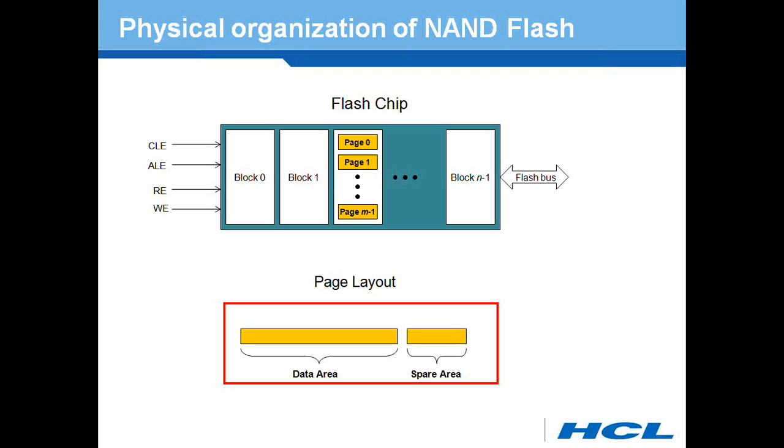Some of the flash manufacturers store this invalid block information inside the flash before it gets shipped to the market. With the help of that invalid block information, we can design our system to handle the reads and writes without using those blocks. They also guarantee that the first block, block 0, present at the block address of 00, will not lose data reliability until 1000 erase cycles.